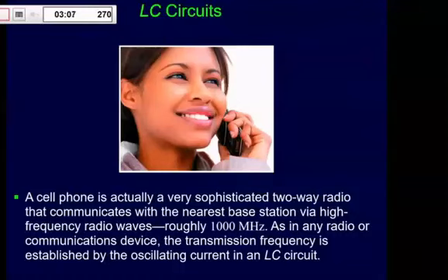If you have an LC circuit, it's just like when we talked about the idea of resonance, back in 2A. If you try to drive these circuits with some frequency that's not close to their resonant frequency, which is this one we just found, you're not going to get much current.